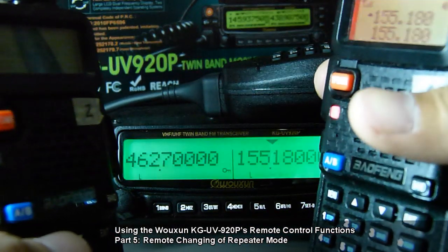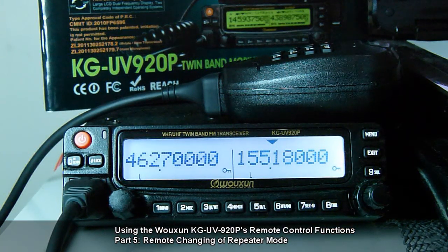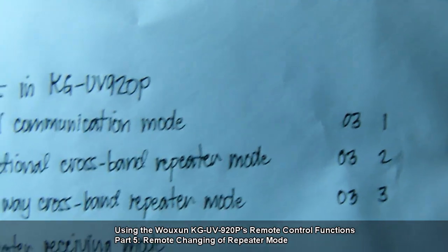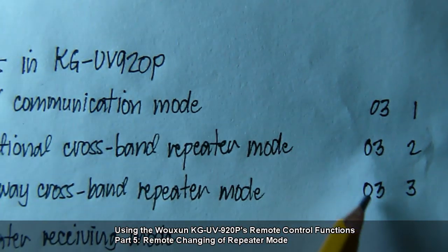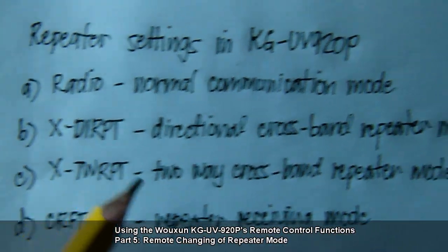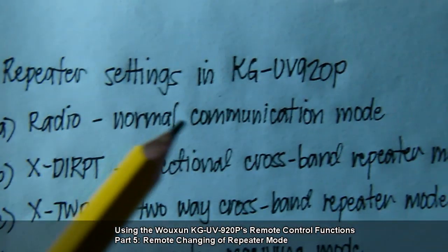So it's normal communication mode. 462.700 is not receiving anything. Now, what if we would like to shift from normal communication mode to directional, two-way crossband repeater mode. Two-way crossband repeater mode would use code 033. So the matching mode code for two-way crossband repeater mode is 3033 to change to two-way crossband repeater mode from normal communication mode.